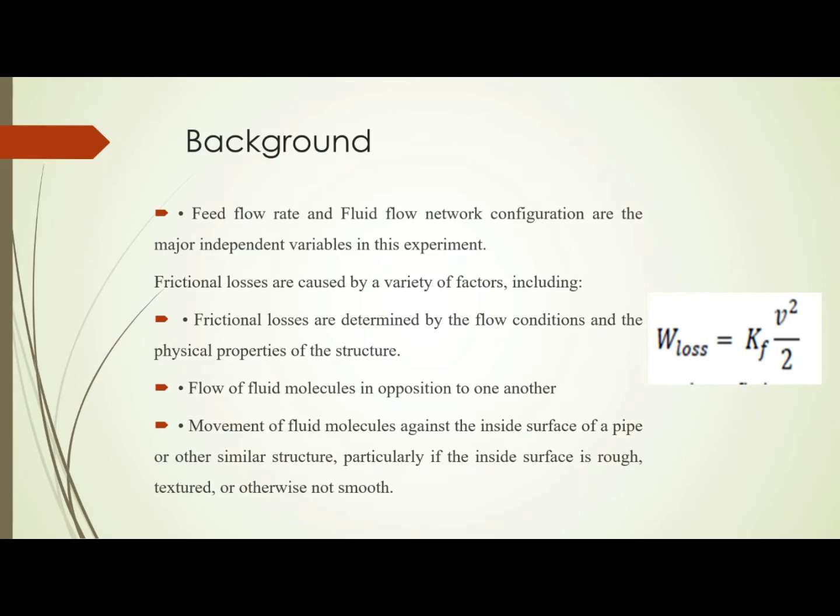Okay, next I would like to talk about the frictional losses in fittings. From that we can calculate the friction losses by using the factor Kf, where W loss equals Kf times V squared over 2. Then you will get the W loss.